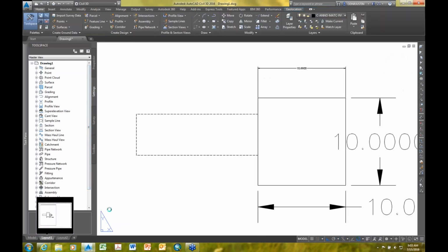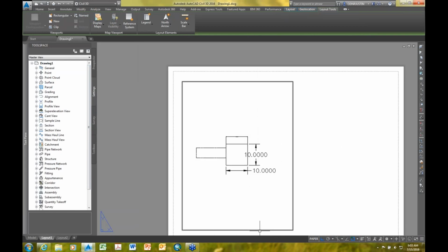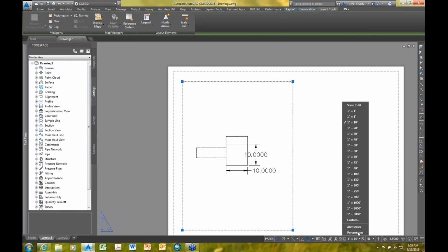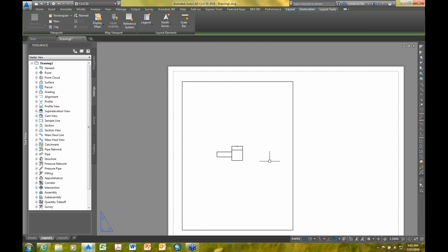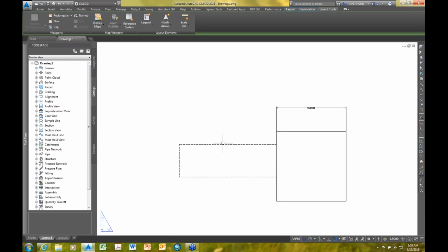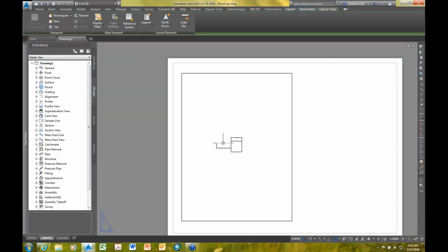The problem with that will be that if I come into my viewport here and scale that at all, that dashed line is not going to scale, and you're going to kind of lose it at some point. So not telling you how or what to do, but that is an option for kind of playing around with getting those line types scaled right.